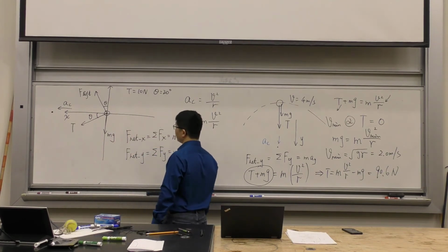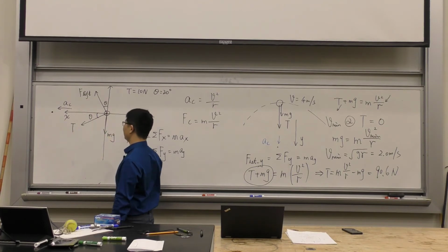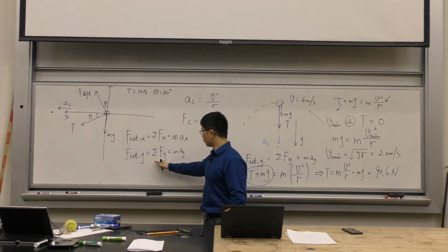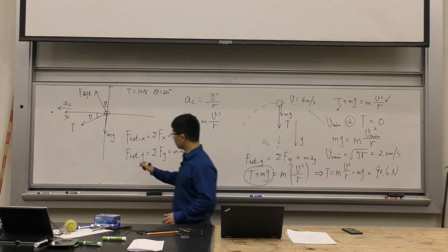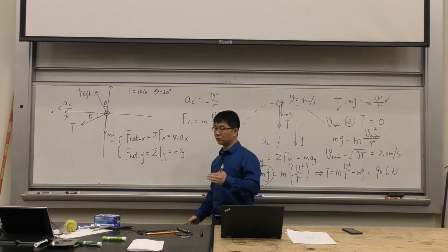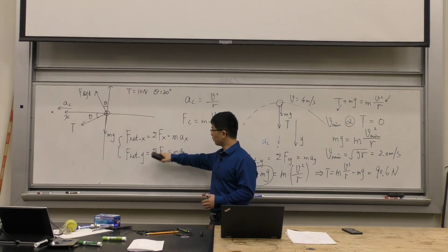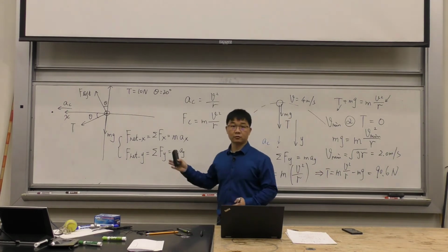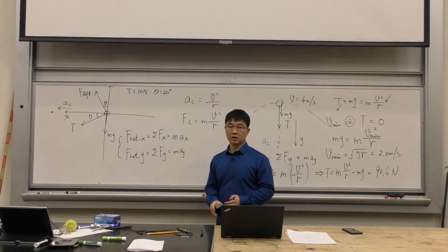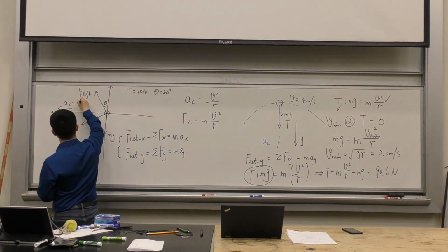Nice. Now in y direction, I will have this, right? This guy also has a y component, you break it. This guy has a y component, you break it. So you will have one component up, two components down. And that's the forces you put in this y direction. Okay, so that's going to be our goal. We're going to break every force into x and y directions, put the x components here and the y components here, and then rearrange and manipulate these two equations so I can get v, because v is going to be in the centrifugal acceleration equation.